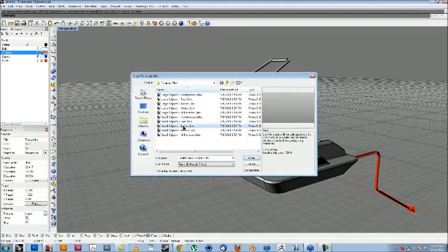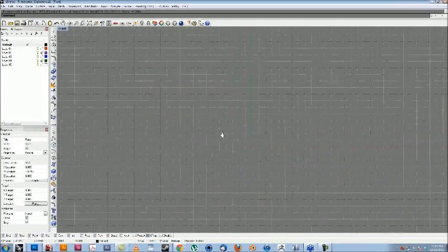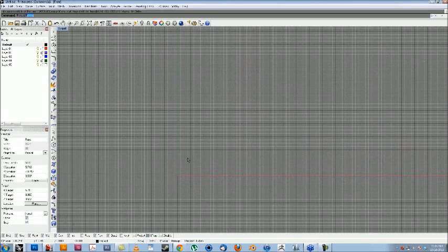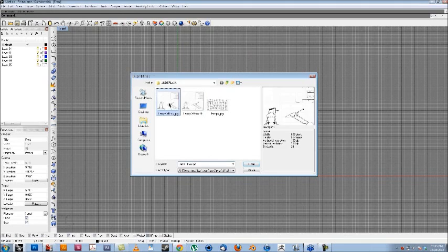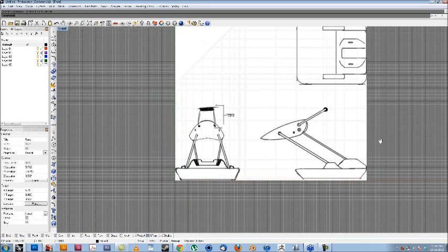And come into inches here. And there's a great command within Rhino called picture frame. And I'm just going to type everything out just because it's a little bit quicker for me. And we're going to use the lamp ortho JPEG here, and I'm just going to specify 0 as my starting point. You can drag out an image.